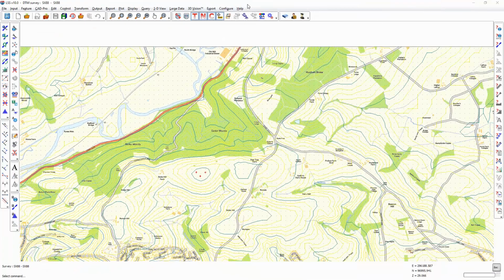I've talked all along about the fact that this data is bald earth data. So what happens if we want to add 3D objects into the terrain to act as mitigating features to affect the ZVI calculation? One such example would be to add this woodland.